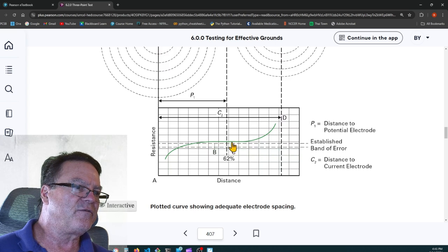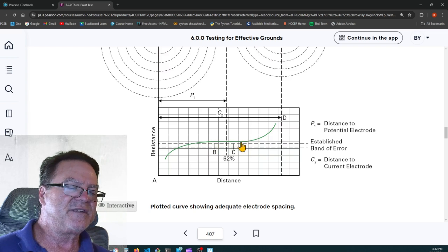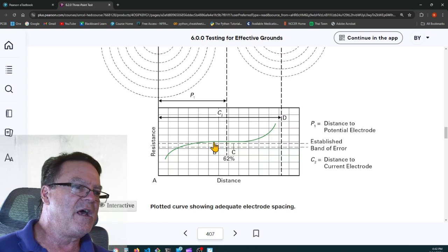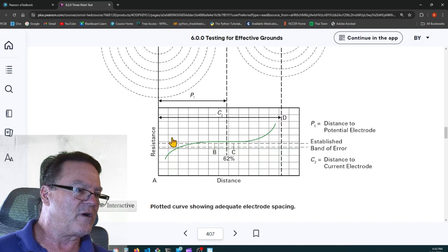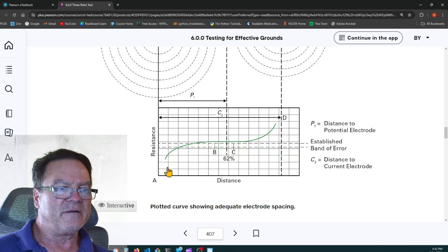Well, this graph that levels off, that's the actual resistance of the earth, of the ground itself. It might be 7 ohms, it might be 10 ohms, but you can use that to calibrate the resistance of your ground rod. You'll have a ground rod, and you can use that information to calibrate it.